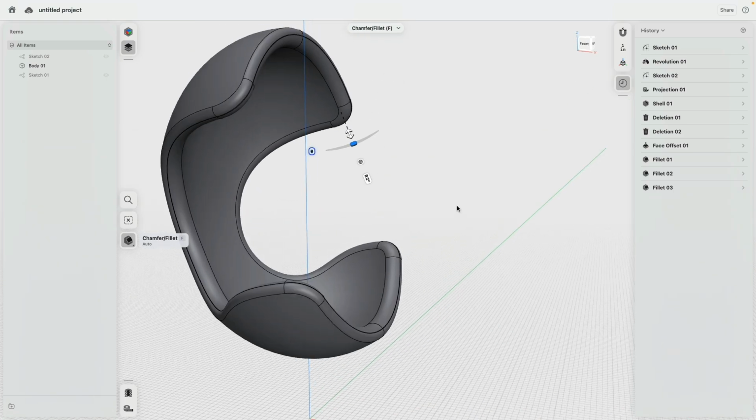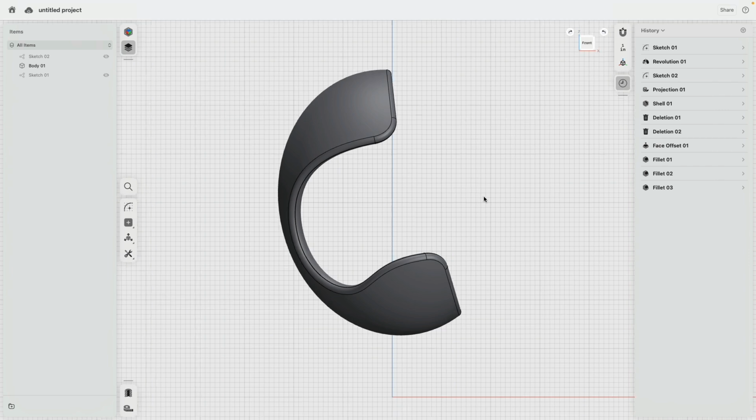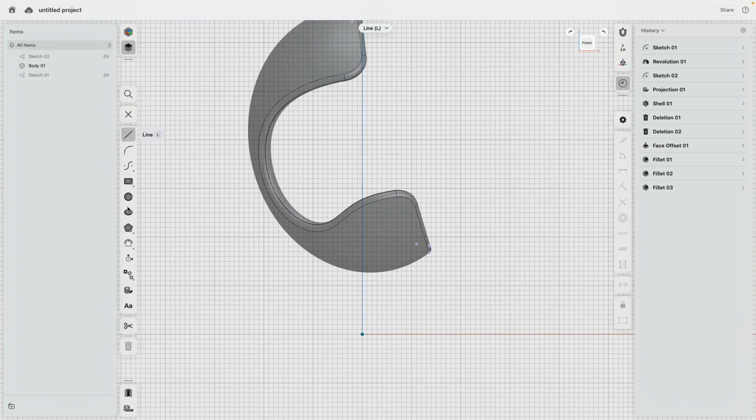Okay, beautiful. This actually looks pretty good. I would say at this point, the shell is done. Then let's make the leg. The legs are really fun to do. And also the process of how we can adjust the legs is a really great demo of how easy and flexible Shapr3D is. With the spline command, I just draw a spline down there.